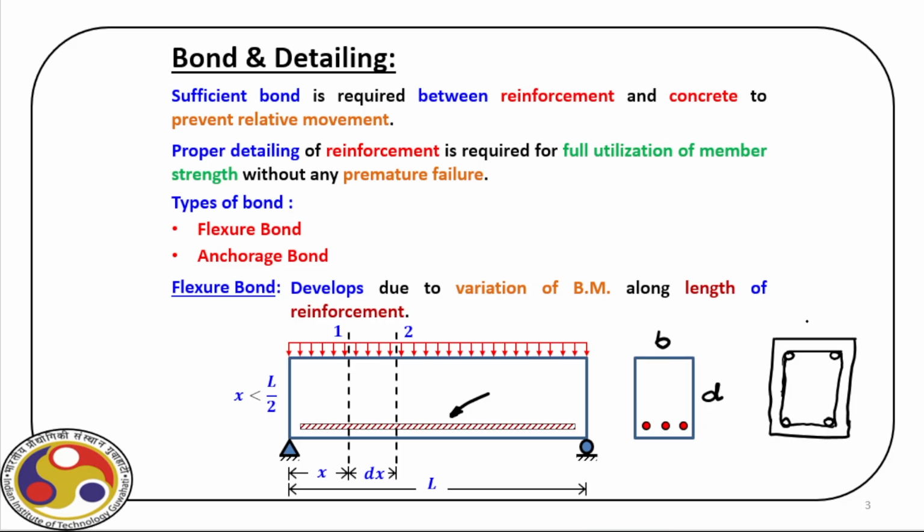Now, when we pour concrete, before that, first we make a formwork here, a rectangular formwork, and then we place the steel. So this is the formwork. Then within the formwork, we first place these rebars, and then once it is done, we pour concrete here, and then we cure it for 28 days, and then we remove this formwork, this shuttering, and then we get the shape of a rectangular beam.